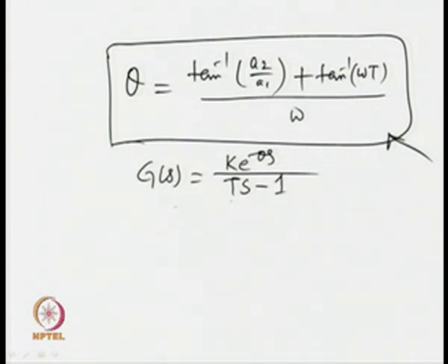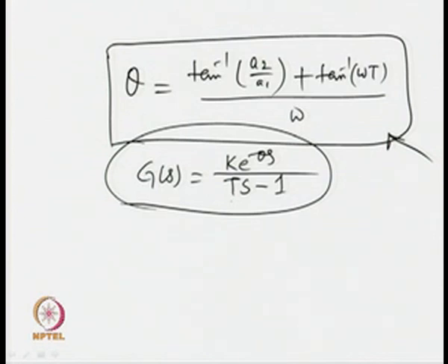Please keep in mind, when the plant is having unstable dynamics, the transfer function model is a first order plus dead time model, including 3 unknowns k, theta and t, and this expression for t and theta we have found, and k has been obtained using the ratio of average values of output and input.